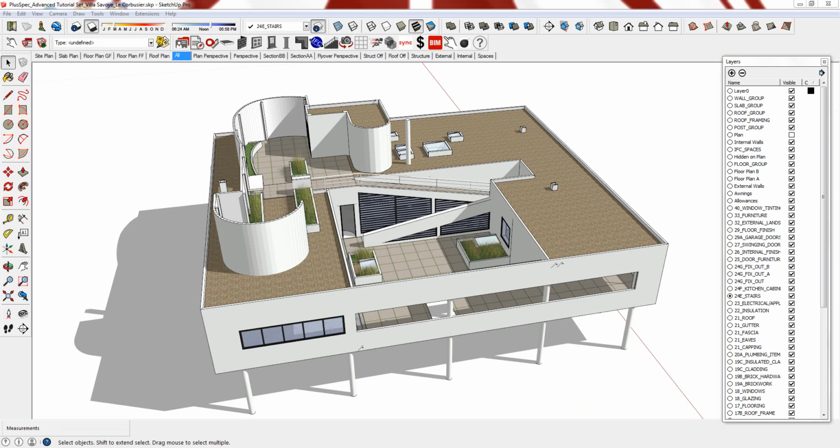and manipulation. Essentially, layers allow you to categorize each item in your drawing so that you can easily control and identify every element in your model. Further to this, layers allow you to control the visibility of each category. Layer 0 is the default layer, and I recommend that any CAD lines or freeformed components, etc. are drawn on this layer. Therefore, ensure that the dot is always assigned to layer 0.